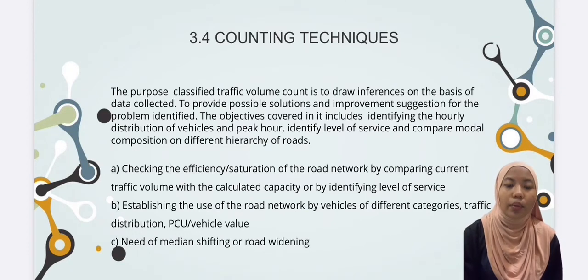Last but not least, I will explain about counting technique. The purpose of classified traffic volume count is to draw inferences on the basis of the data collected to provide possible solutions and improvement suggestions for the problems identified. The objectives covered include identifying the hourly distribution of the vehicles and peak hours, identifying level of service and comparing modal composition on different hierarchy of routes.